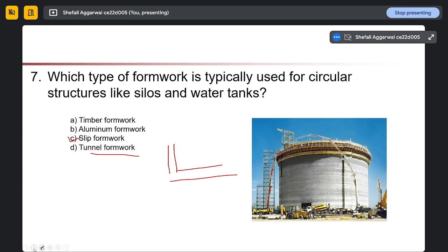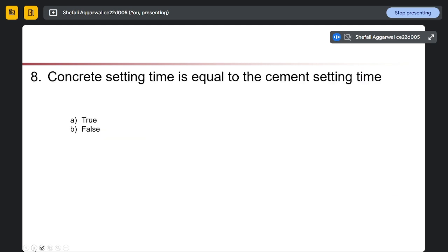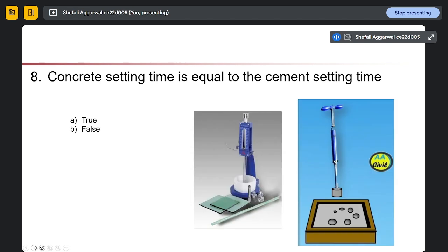So mainly early strength is because of tricalcium silicate. C3S has a high silica content because of high calcium oxide content. It will contribute to early strength development. If we see even from our hydration curve, this acceleration period is mainly due to the hydration of C3S, which contributes to the higher early strength in the concrete system.